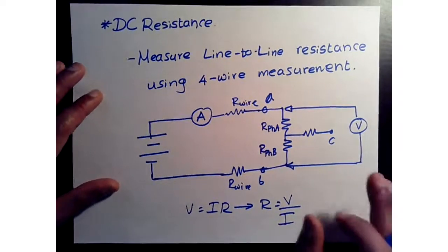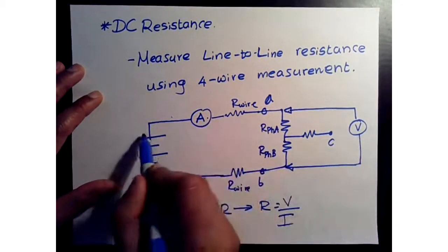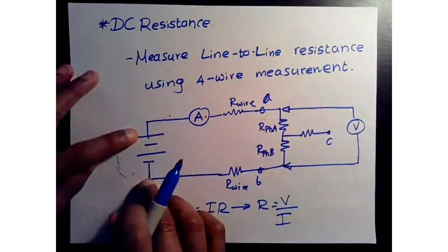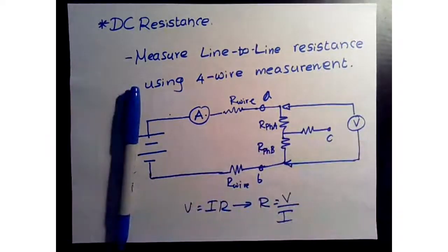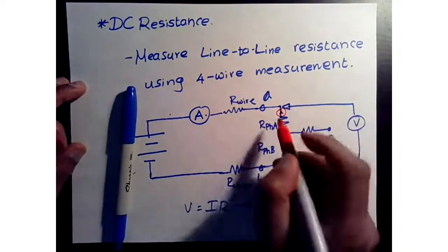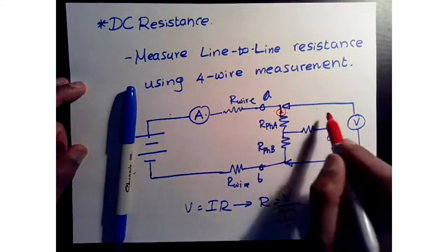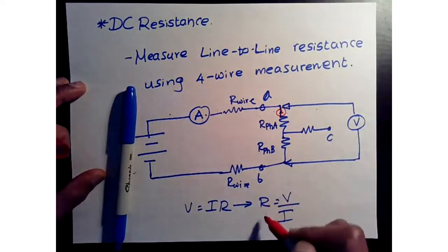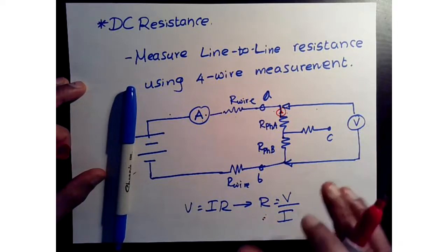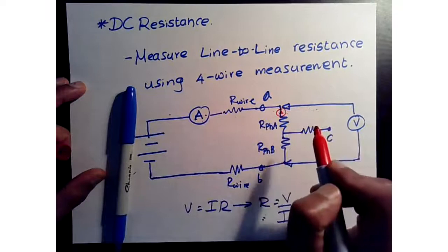Now, what's the other way to do this? Well, you can place your voltmeter here, or you might want to use the voltage that you're supplying. Or if you move your amp meter in here, right? All these will add some resistance to the measurement. That way your voltage measurement might have some error, and it will carry over to your motor resistance value and might make it incorrect. So that's why we try to have the amp meter before the voltmeter.